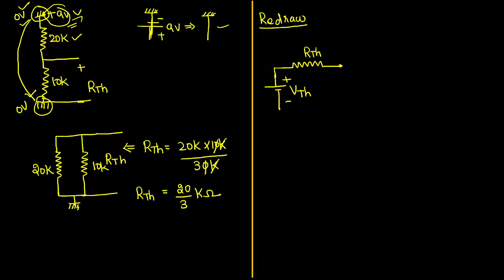Then this resultant node is going to be connected with what? The load. Which is the load here? Our transistor is going to work as a load here. So I am just reconnecting the transistor. The entire transistor, we are treating as the load. So this is how we are redrawing the circuit. Here, this VTH is simply considered as VBB. RTH is simply considered as the base resistance RB. Now see, a single resistance and a single voltage.